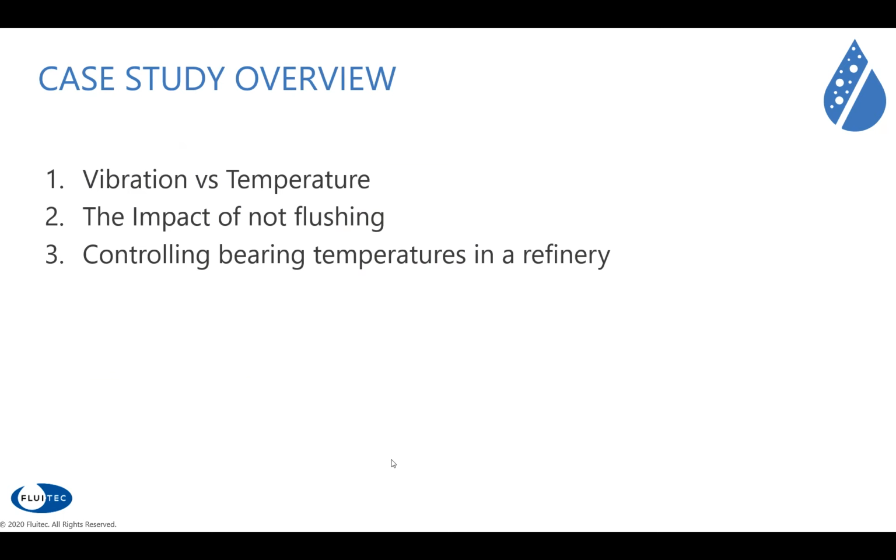Very first interesting case study is an offshore gas platform with gas turbines, where we noticed interesting behavior. Again, you will recognize the red lines or the spikes of the temperatures on this bearing. And within the time, you can see that these spikes become higher and higher until even the gas turbine has to go out of service. We see that also in the blue line. First one is vibration, slight effect of vibration, but bearing 2, which is apparently a more rigid bearing, is clearly reacting, and you can see that the amount of vibration signals is clearly increasing.